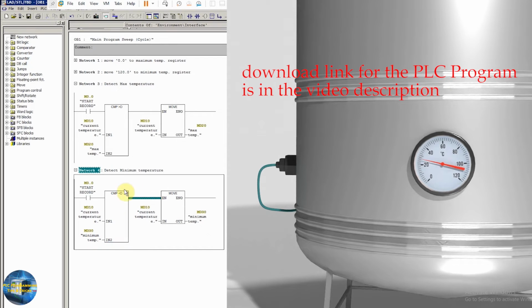As we are using a less than comparison instruction here to detect the minimum temperature, this instruction becomes true and it will move this 15 degrees into this MD30 minimum temperature data register, and the same will be updated here as well. Now our minimum temperature is 15 degrees and it will stay there, and let's suppose that after some time the temperature drops to 10 degrees.